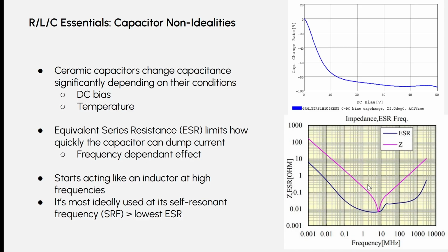It's not super critical. Effectively, what this means is that if you have some AC signal, the frequency will very heavily affect how the capacitor acts. And so at a very low frequency, compared to a high frequency, compared to what's called a self-resonant frequency, you get very different behaviors in terms of the resistance of the capacitor. So a very low resistance means the capacitor doesn't have to work very hard. It's very capable of filtering fluctuations.